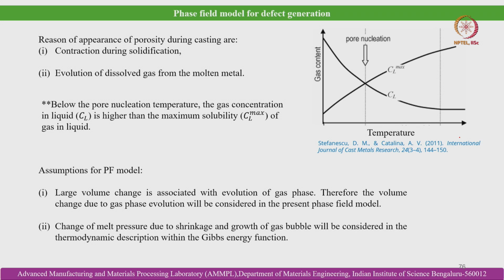So, you can see that from here we can predict the microstructure evolution, and also we can reduce the number of experiments, and also we can tune the process condition and alloy composition to get the desired microstructural attributes in the solidified object. So, we can basically do microstructure engineering here, so that we can derive the desired mechanical as well as functional properties in the solidified parts.